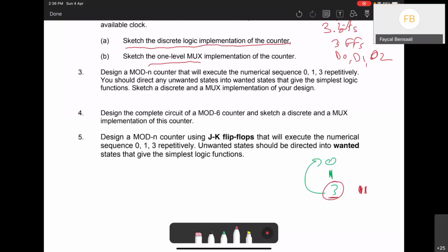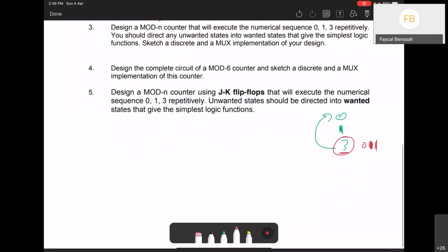If I use 3 states or 3 flip-flops, of course it's correct, but you'll be wasting your resources, because for the last output, it will always be 0. So the last flip-flop, we know in advance that it always gives you 0. There is no point to do this, right? So we have 3 states, 0. In such examples, there is no need to draw this state diagram, right?